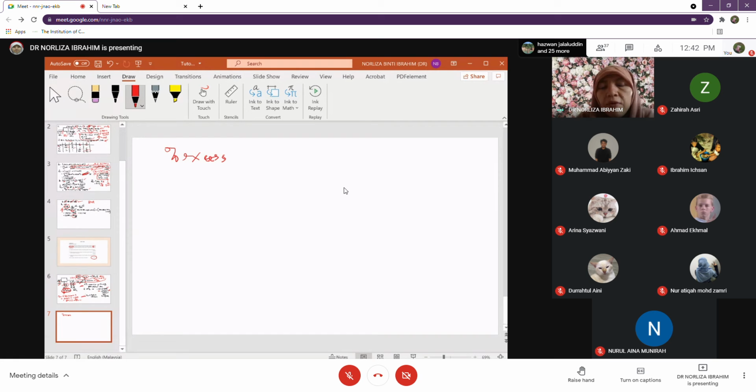So if 90% excess air is mentioned, it is actually the same as 90% excess oxygen. So I'm focusing on the oxygen. Oxygen feed minus oxygen stoic over oxygen stoic, times 100%, because it is a percentage.